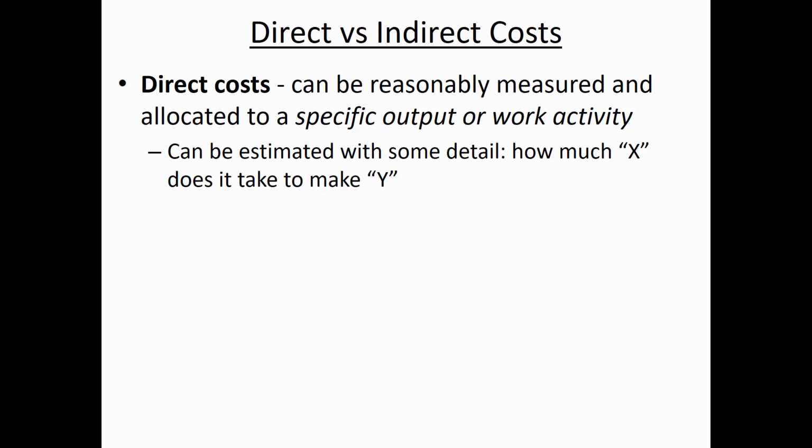The guy that I ended up choosing was the one who got out a tape measure and actually measured how wide the driveway was going to be, how long the driveway was going to be, looked at what the existing subgrade is, is there already a good base of gravel that we're going to be able to use, or does it all have to be removed? Then he's thinking, where am I going to move all this used asphalt? So the removal expenses. The one who was able to think through with a little bit more precision on the different components of the project is the one I ended up choosing, because I had the most confidence that the estimate was reasonable, and that that person was planning ahead and not just making it all up.